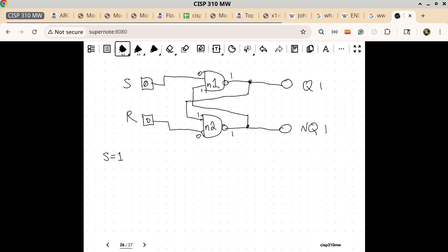All right. The first thing we do is say, because of node connectivity, we also know that N1.in[0] is going to change to a 1. And that's almost instantaneous. For the purposes of this class, we can say the wire is instantaneous.